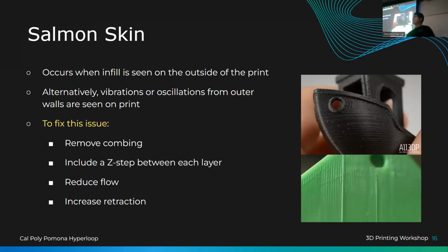Basically, the idea is that the stepper controller within the stock Enders is so bad that you have to work within limits. We can define layer heights, which is the height per layer. Higher layers are bigger, more gappy, salmon-skin-looking, but lower layers take more time to print and look a lot smoother because you're doing more passes per millimeter.